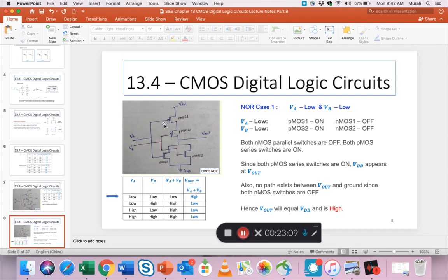We don't need huge resistors in the drain circuits, right? To get all the benefits of CMOS, we always need to make sure that they exist together. So for every PMOS, there has to be an NMOS. So these have to exist, and we have to make sure that they cooperate with what's going on the top. Otherwise, your circuits are not going to work.